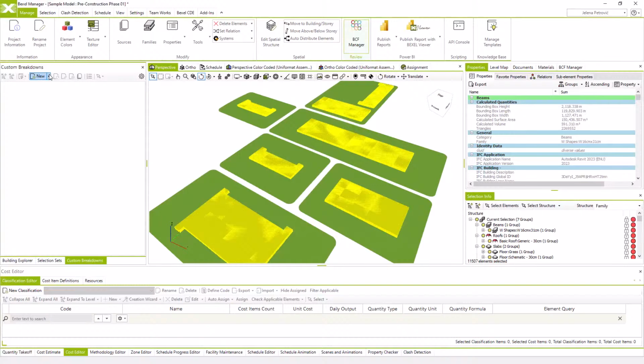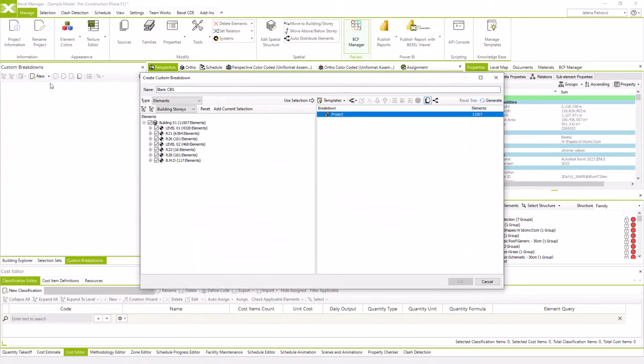Choose from selected elements option, and the name can be the name of the property we will use, like in our case IFC description, where we have information about buildings, or we can just call it buildings. Elements are already selected, so just click on Use Selection command.